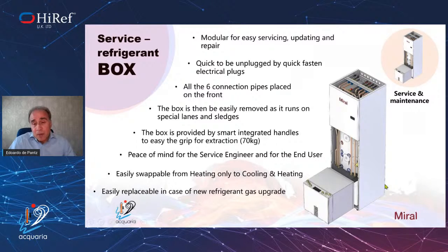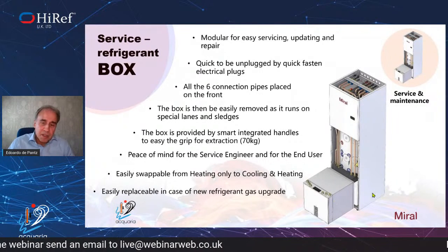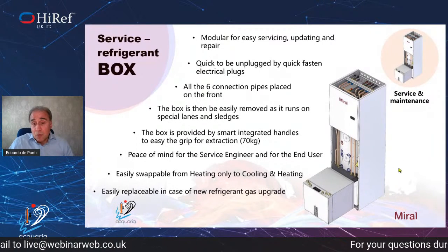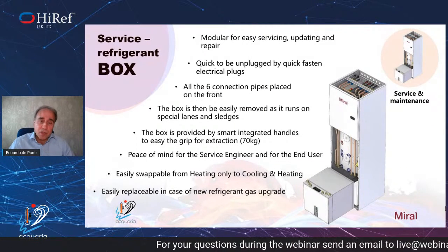So it also means double installation, but mainly for quick dismantling. If you need to service the units or make some intervention, you can easily unplug the electrical cable in this position. You can unbolt the 6 pipings on the front of the units. You can easily extract the box and take it to the service station for a very quick and easy installation, repair or service of the unit.